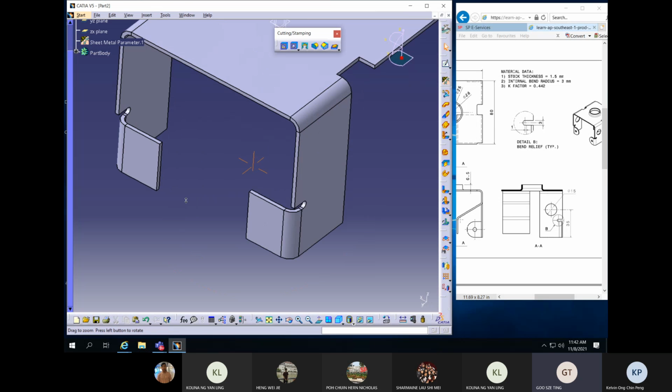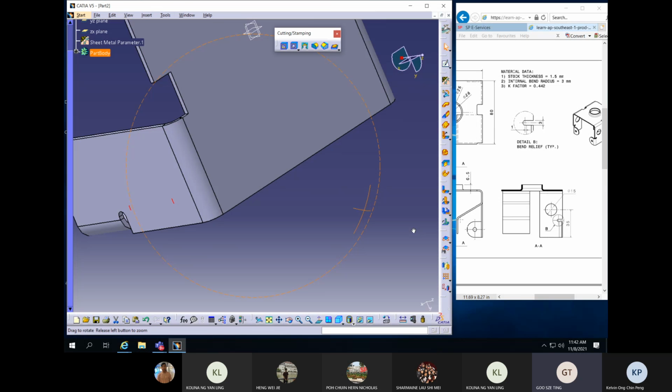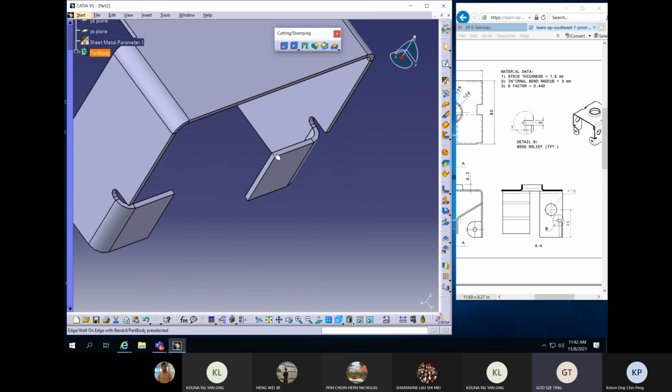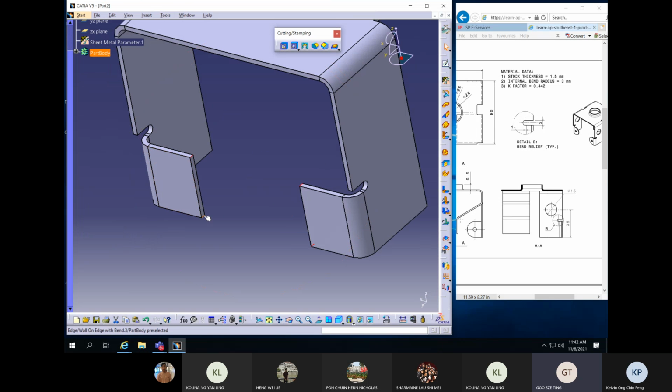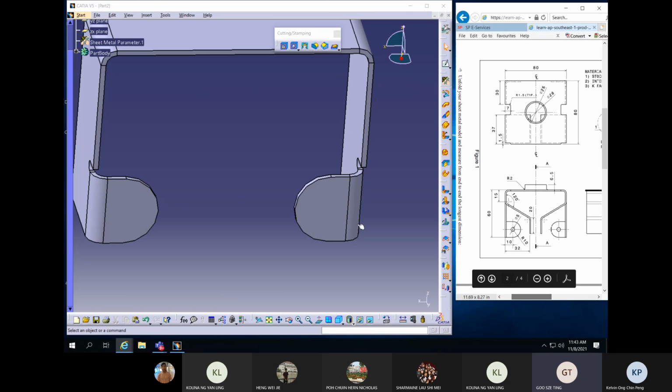So here is 20, right? So basically, what's the radius? 10, right? 1, 2, 3, 4. Do a radius 10. Finish. That looks proper. There's a hole here, right? You can do the hole, radius 10. So circle, hole command.